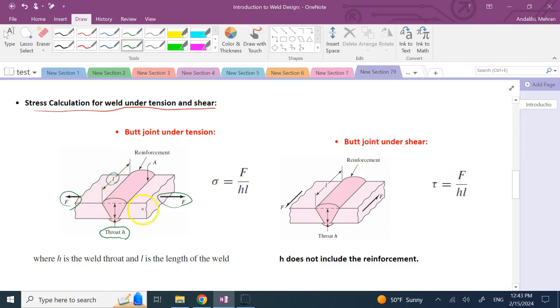And here, in this case, the weld has a reinforcement. What is reinforcement? Reinforcement is this extra projection of the weld bead out of the part, okay? So here it's not completely sanded and made flush. This extra portion on the top of the part is remaining for reinforcement.